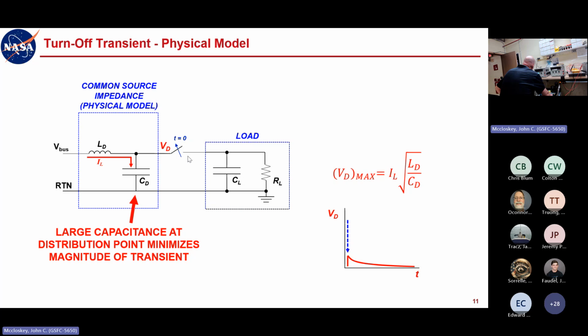And so it's important to understand that if the largest dip that you can expect to see on your platform is on the order of half a volt, then it doesn't necessarily make sense to test your hardware with transients going down to 0 volts.